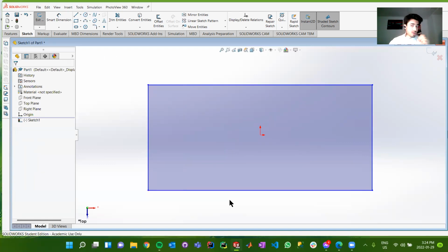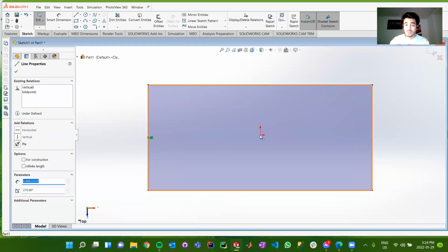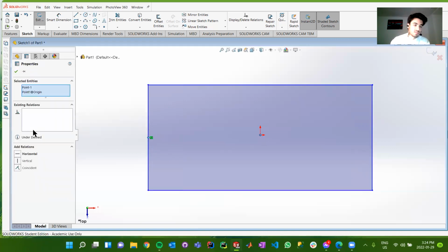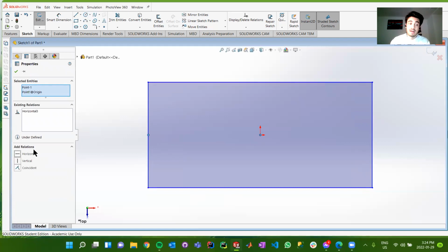And from there, if you try to move a single component of the sketch, you'll find it won't budge, because you've defined it in a way that it's stuck the way it is, and it already has a set of relations that will not allow it to move freely. To get to this stage, I'm also going to constrain this midpoint as well, such that it can't move. So now it's a horizontal constraint.